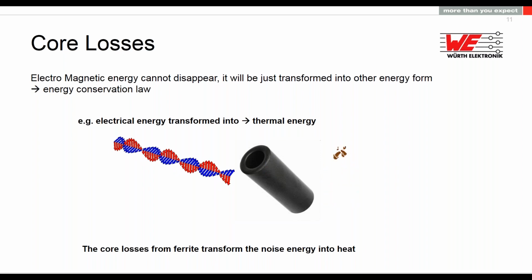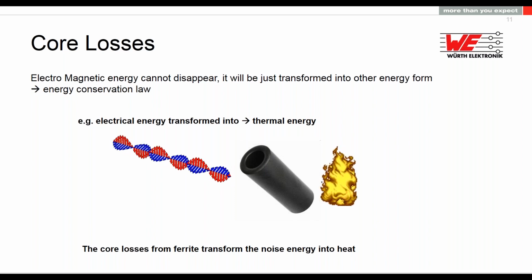But believe me, even if you use a very sensitive thermal camera and look at your USB cable ferrite or VGA or HDMI ferrite, you won't see any temperature rise there. But if you ever build machinery and you put a ferrite core on your cable and the ferrite starts running hot, I can tell you, you don't have an EMC problem any more. You now have a safety problem, and I suggest you run away as fast as you can, because this is no longer an EMC problem. You're not talking about 10-20 volts per meter, you have several hundred volts per meter when the ferrite starts running hot.